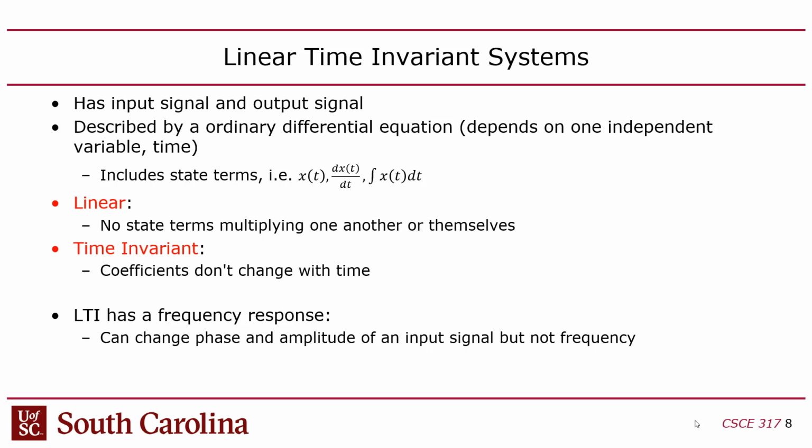You guys ever heard of Z domain? So Z domain is the equivalent of S domain, but it's discrete. It's not continuous. And you can also have a discretized form of state space as well, even though state space is technically continuous. But here's the problem then. Your plant is going to be a continuous system and your controller is going to be a discrete system, and yet somehow you need to combine all this together, and to simulate it, hopefully to be able to tune your controller to make it robust against disturbances.